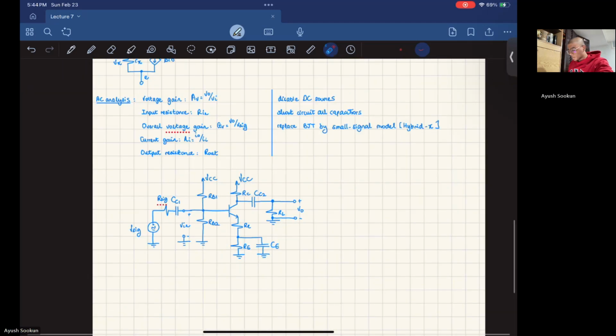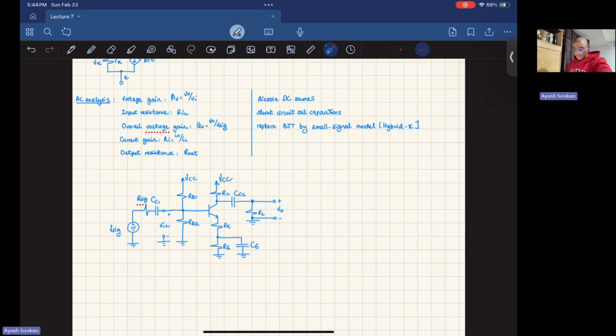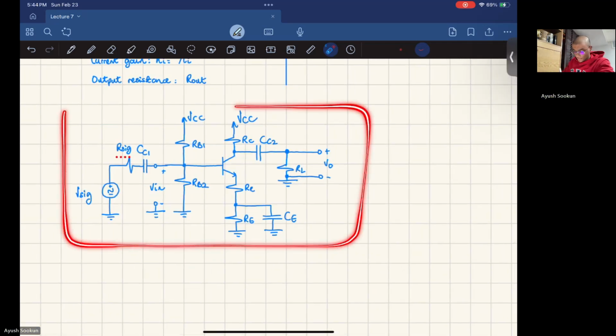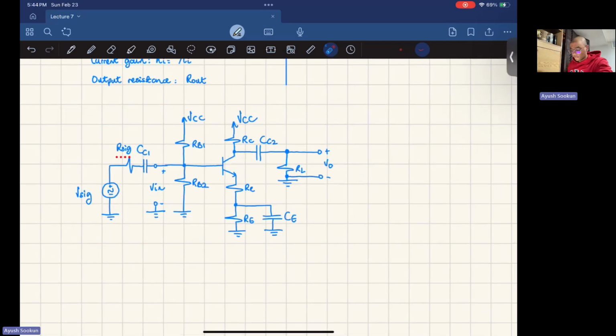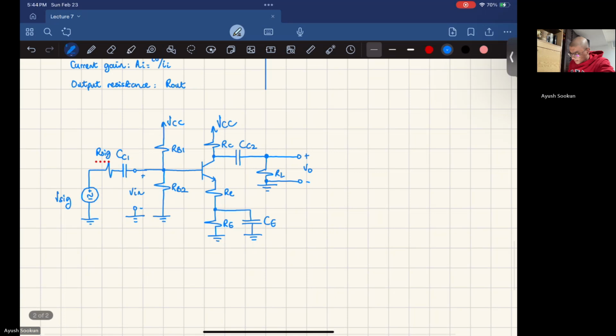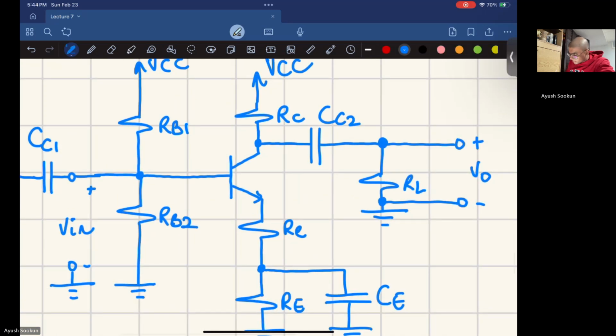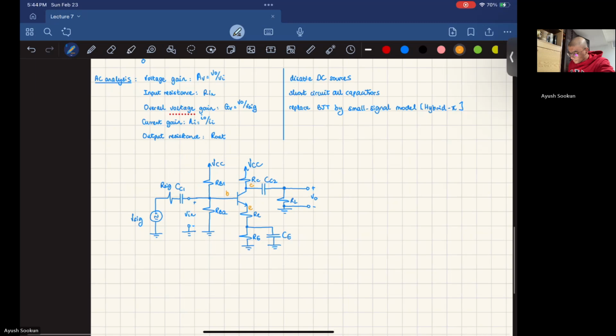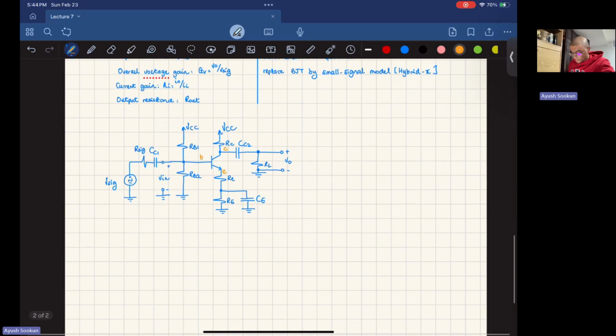So without further ado, given this sort of situation, this circuit might look super big at first, but trust me, it's not that bad. In this video, I am going to be writing everything out. The first thing I want to do is identify the base and emitter, and I want to disable my DC sources.